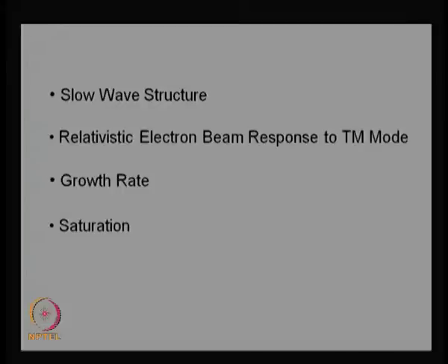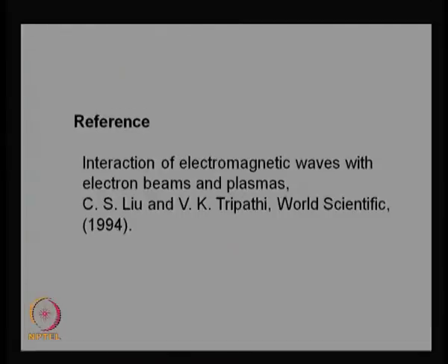The device is quite interesting. I will discuss the simplest structure that can slow down a wave, and then I will discuss the interaction of an electron beam with a transverse magnetic mode of this guiding structure. We will derive the dispersion relation, obtain the growth rate, and discuss the saturation of this instability. Well, this is the reference.